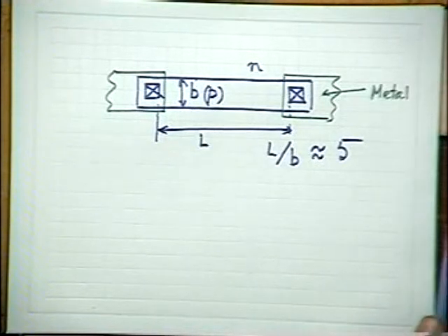So you see that in bipolar integrated circuits, resistors cannot be avoided. Excepting for I2L logic, in all other bipolar integrated circuits, resistors are essential, and these resistors are realized normally using the diffused layers. So what is the problem of these resistors as compared to the resistors which you use in normal circuits?